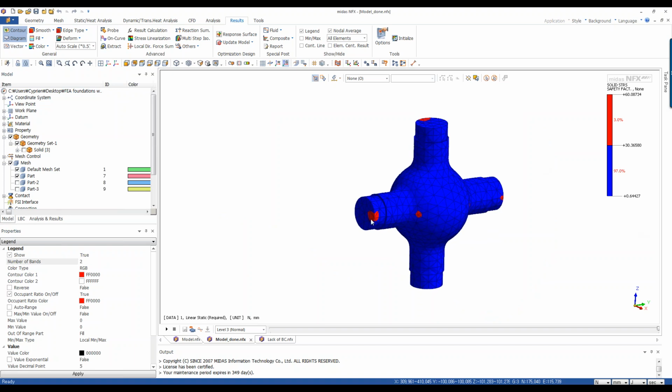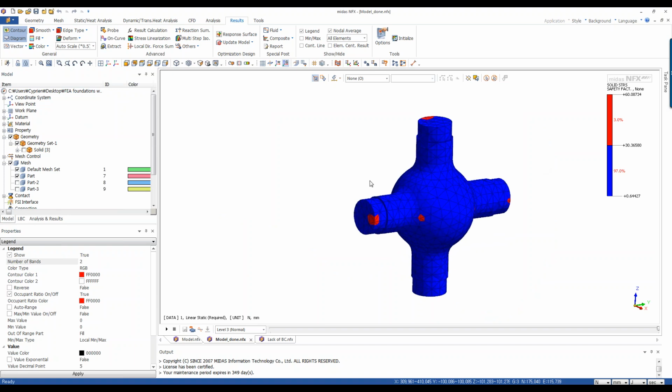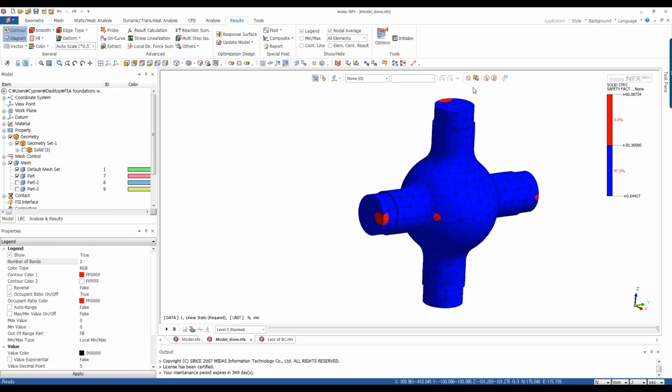Because we are using the FEA method, sometimes we can obtain peak stresses, and the places where the peak values are telling us that there is a stress concentration, but not every place is the right one, so we have to make some judgment on the model as well. And we have to learn how to display contour maps in a reasonable way.